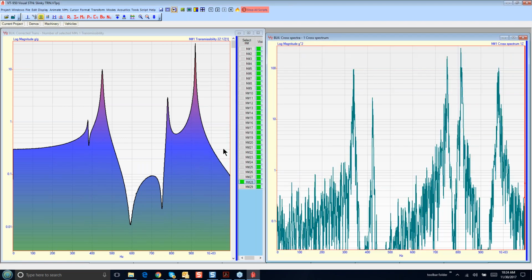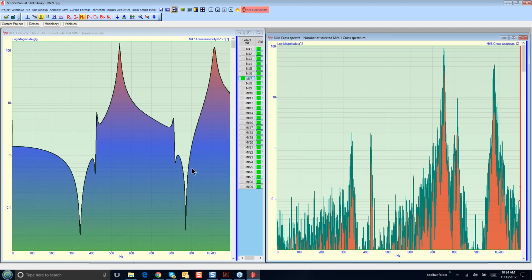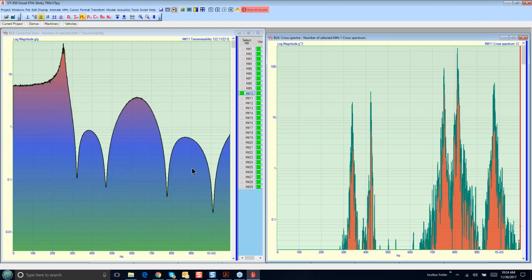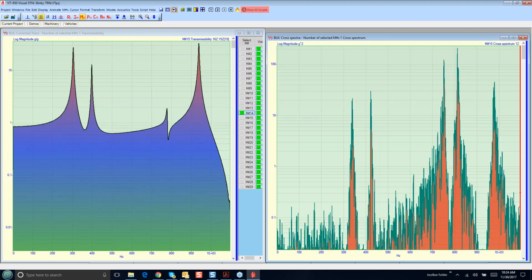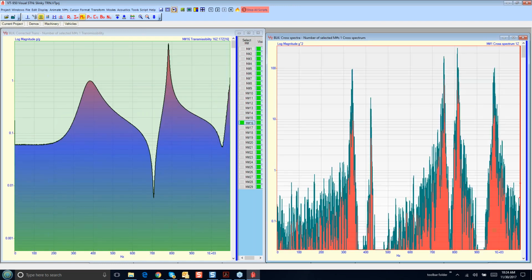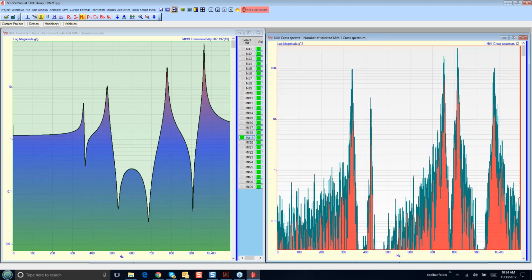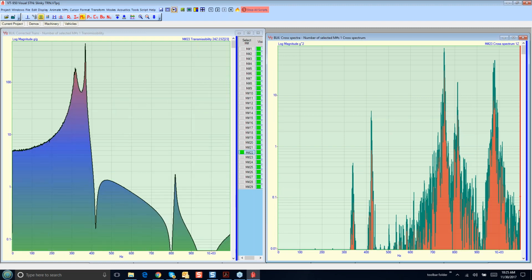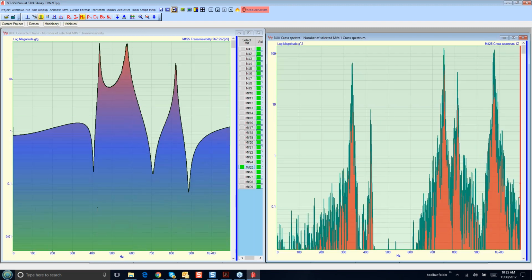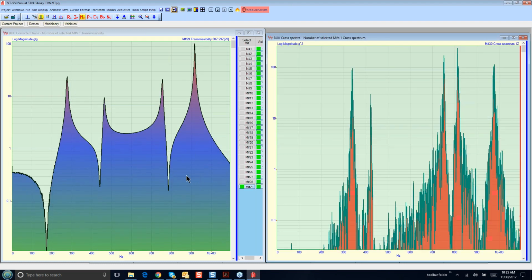If we're going to look for mode shapes by curve fitting cross spectra, which we can do, or simply animating with a cursor in the cross spectra to get the ODS, we need a single reference set. So now we're converting this multiple reference set of transmissibilities into, we're seeding it with a set of cross spectra, actually a single cross spectrum. And then we went through this in September. So you'll have to go back and look at the details of that in that video.